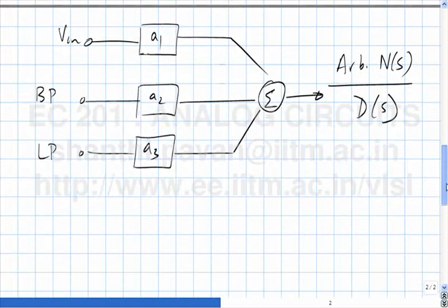And this also reinforces another concept that we have seen earlier. What did we see earlier? If you have a numerator that is a constant, all the zeros are at infinity. Now, if the coefficients of the higher order terms of S in the numerator are not all zero, then the transfer function has got finite zeros. If there are multiple paths from the input to the output, we saw that you will get zeros, and this is just turning the same fact upside down.